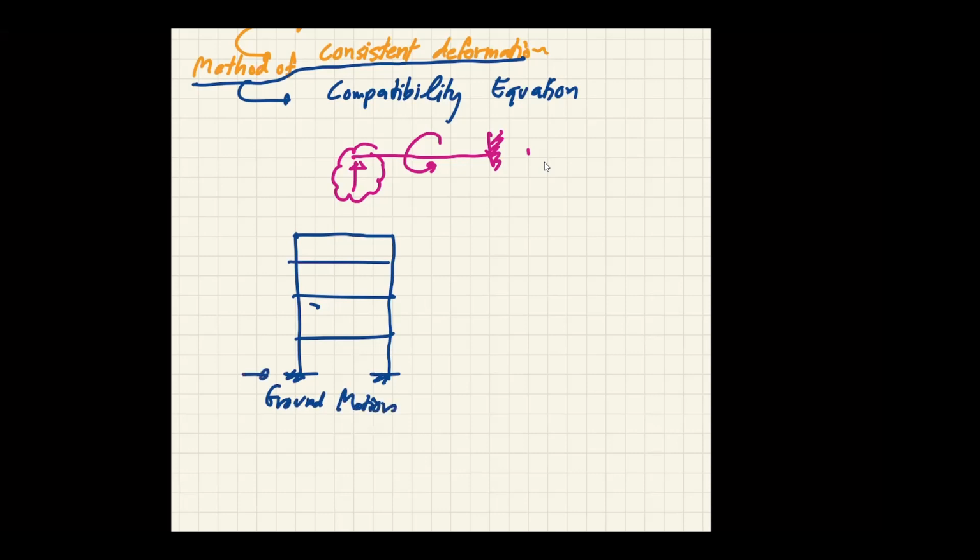And then it can be converted into some kind of shear force acting at every level of the building, like that. Now the concept that they generally require the engineer to design the building is that we no longer design the building by using the elastic method. So that means when the earthquake hits, your building is going to take some damage.